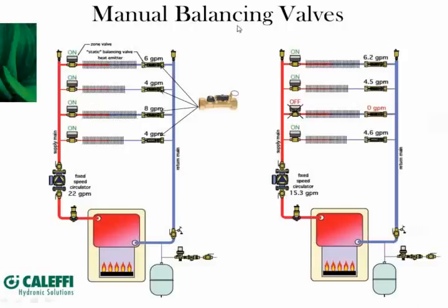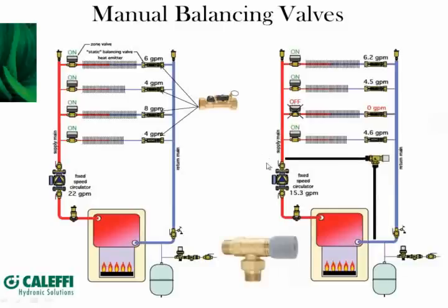That creates problems. Now, before we leave this manual balancing valve example, one solution that the designer could do is install a differential pressure bypass valve from the supply side back to the return side of the pump. This would absorb any excess flow that otherwise gets sent through the zones if you don't use a differential pressure bypass valve, meaning all of the valves stay at their design flow. Okay, so it adds a little bit of cost in doing this, but it keeps you at good control.